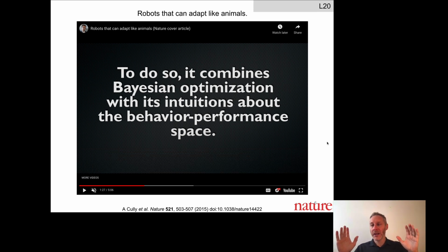The idea here is we're going to try and rapidly recover from damage, but there's always a cost for an advantage, which in this case is rapid adaptation. The cost is that among this diverse set of controllers that work well for the simulated hexapod, they all work well for the simulated undamaged hexapod. So if the hexapod becomes damaged, the assumption here, and it's a bit of a risky assumption, is that there's going to be some controller among all these diverse controllers that worked well for the simulated hexapod and also works well for the physical damaged hexapod.